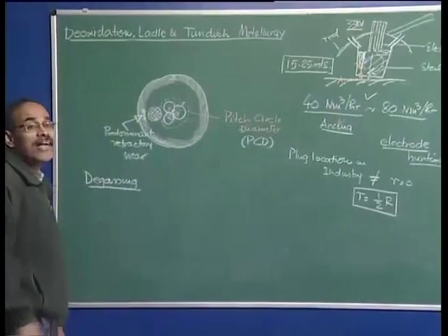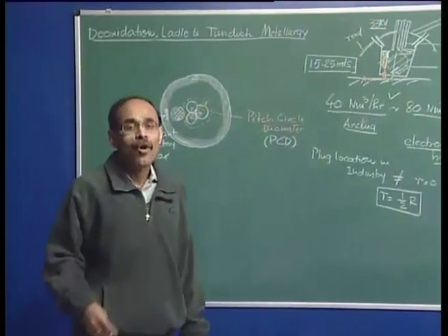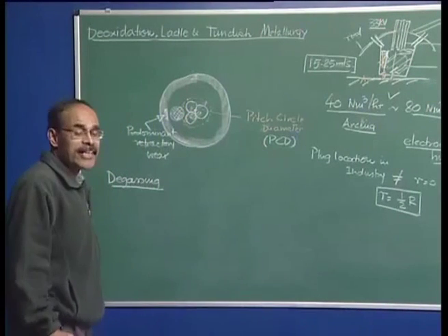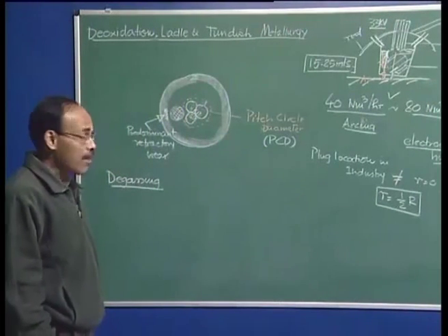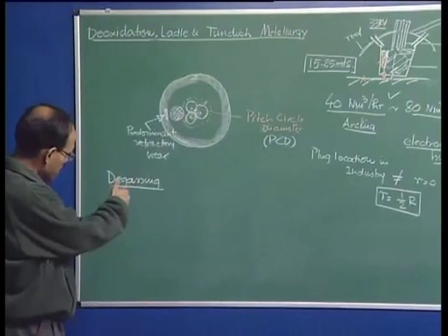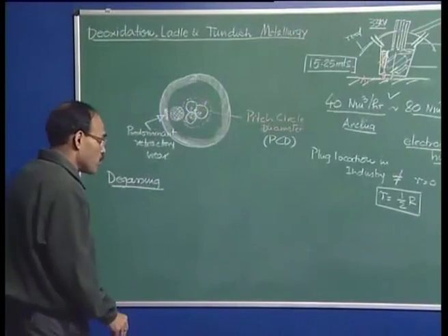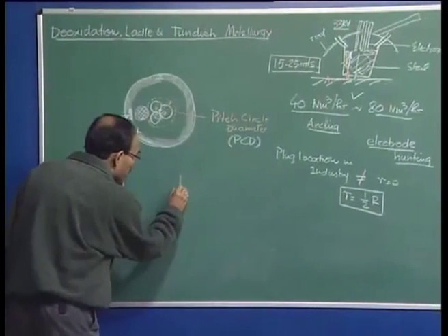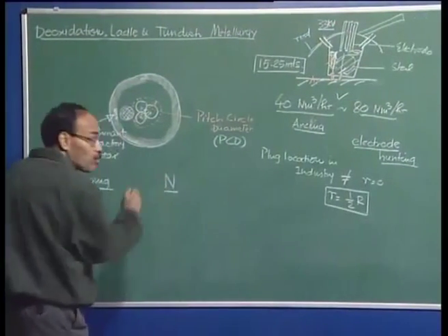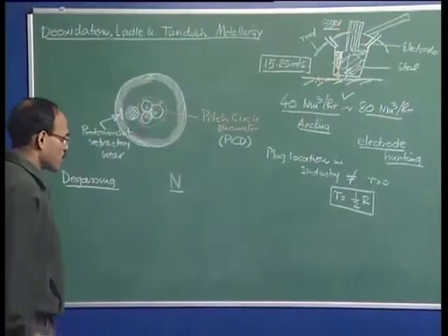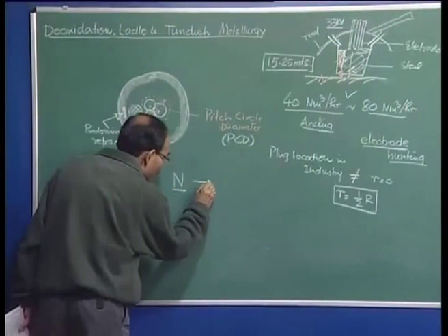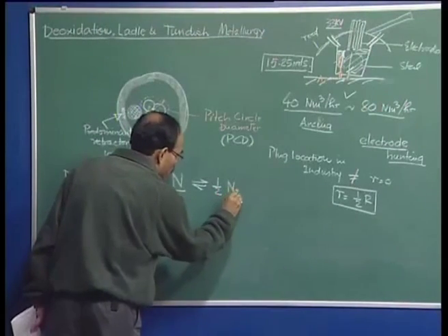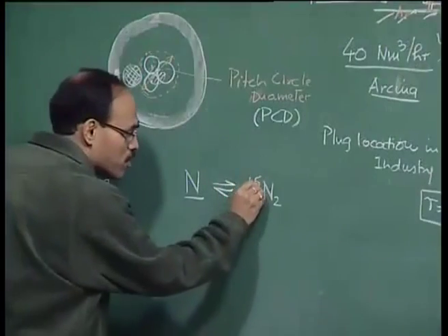And the techniques that are used are commonly called the degassing techniques, and these are basically the vacuum degassing techniques. Degassing will be facilitated under vacuum, and once I tell you the principle briefly, you will understand why vacuum facilitates it. For example, if you take nitrogen, which is dissolved in steel, and then if you consider the equilibrium of this reaction, this nitrogen is driven out of the melt and goes into the gas phase.